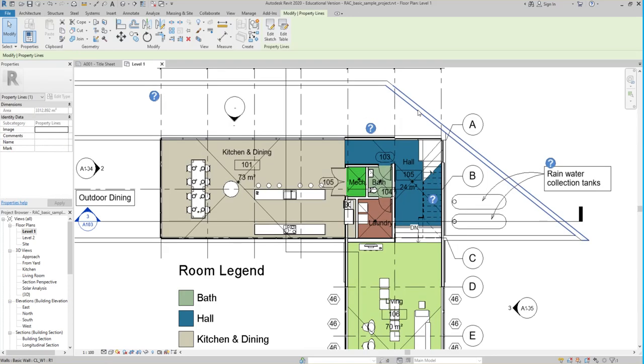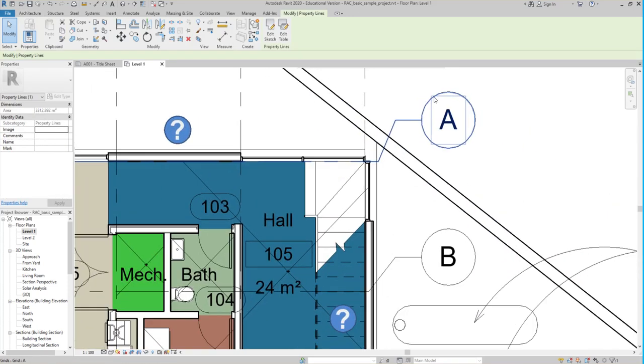Okay. Does everybody understand why we use pen weights then? I mean, really the idea is so that you can graphically read a set of drawings, so you know what is what, okay? And then the idea of where they come from is from the formation of the floor plan, where you cut the building horizontally, get rid of the top, and what you see, the pen weights you see, is really associated with that cut, okay?